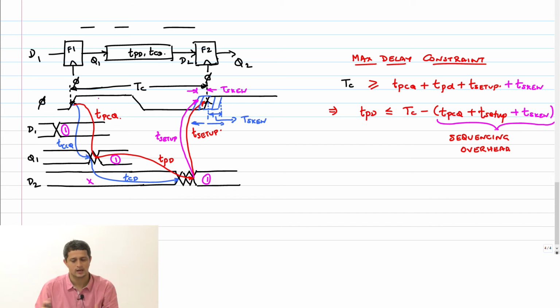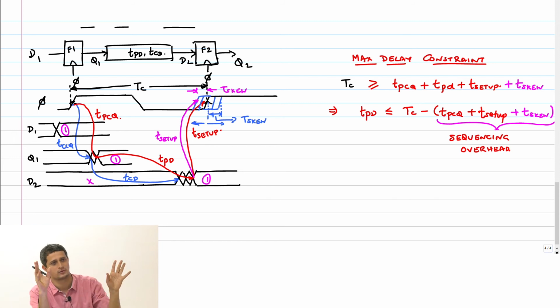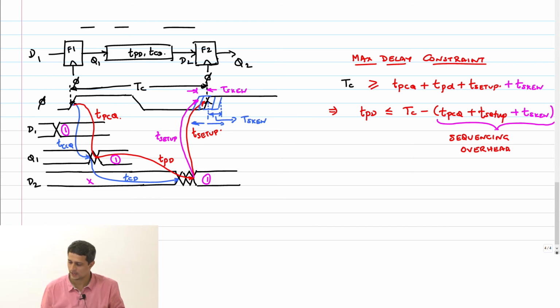Therefore if I consider T skew here once, I'm done, because I've considered between any two random clocks, this is the maximum number. So you could divide it as T skew by 2 here, T skew by 2 there, doesn't matter. It's just one counting. So what he's saying is the T skew definition is the worst case difference between any two clocks on the leaf nodes. That's what T skew is. Okay, so that we have taken care of.